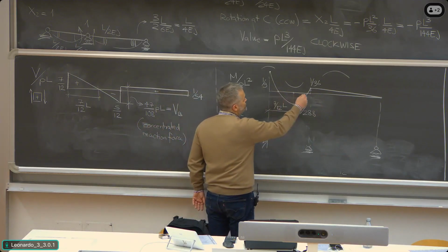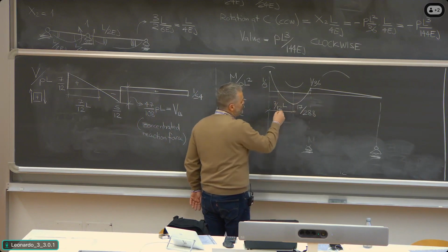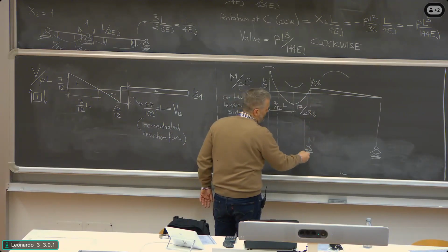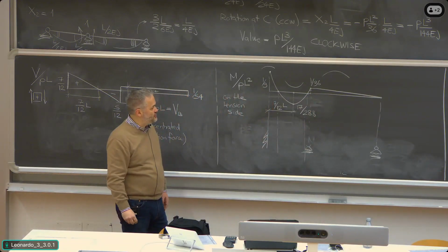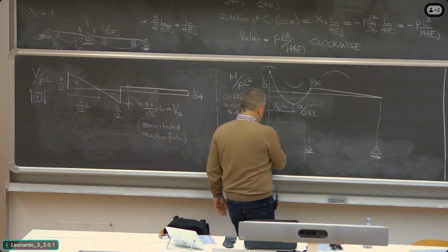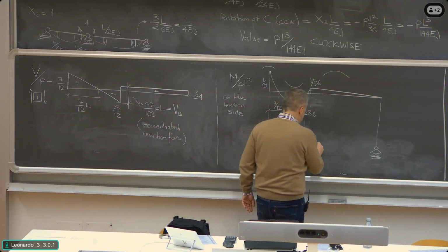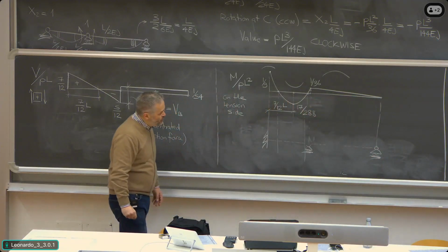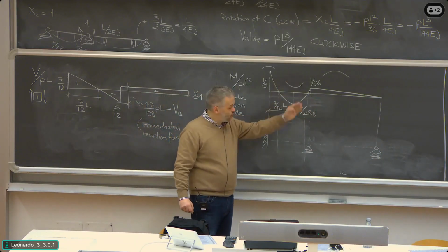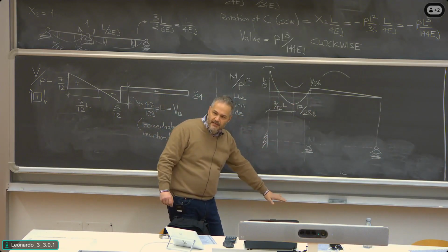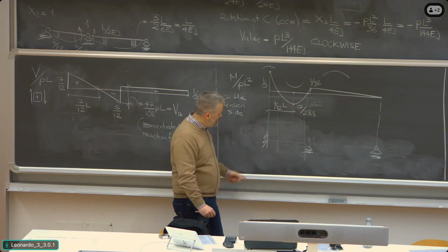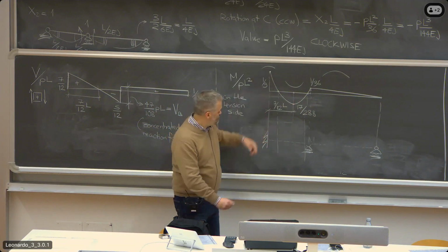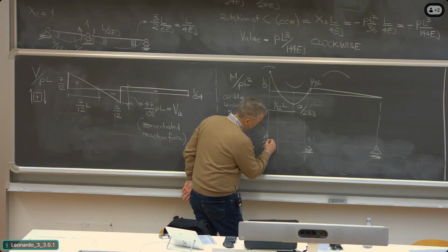What is important is to look at the points where the bending moment is zero, because these will become contraflexure points in the deformed shape. So points where there is a change in the curvature. So starting from the undeformed shape, which I will likely mark here and dash it. What is a likely deformed shape? Remember that here there is a load, so this span is likely to sag downwards. Okay? We have to start with no rotation and no displacement here, and then we have this curvature here. So the starting point will be like this.